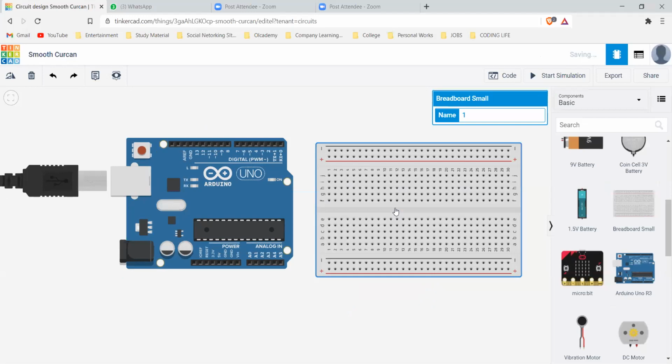So if you hover over, like see, this is the negative one. If you hover, you can see that all the negatives are connected to each other in a series. If you hover over the positives, then it will show you that all the positives are connected. Similarly, below, all the positives and negatives are connected to each other. In the middle part, if you hover, you get a green line indicating that this point is connected to all the 5 here, so it can be connected to 5 different points. So let's begin with an example.